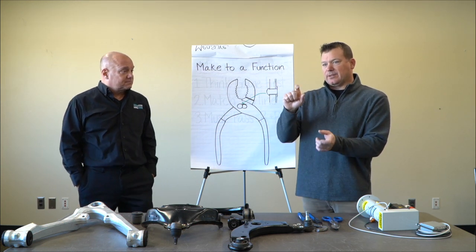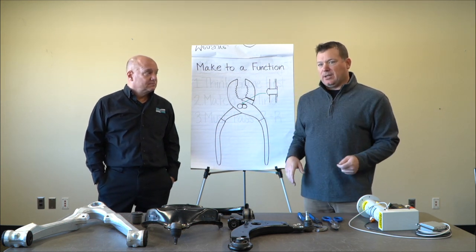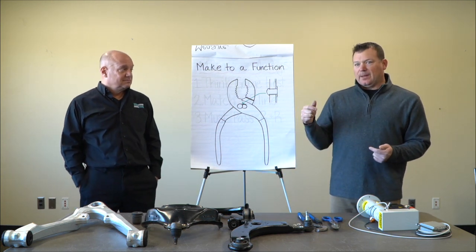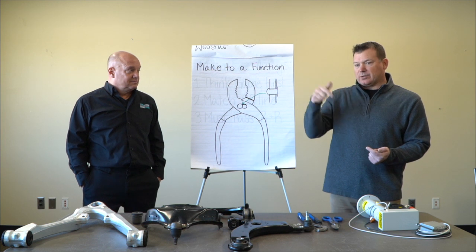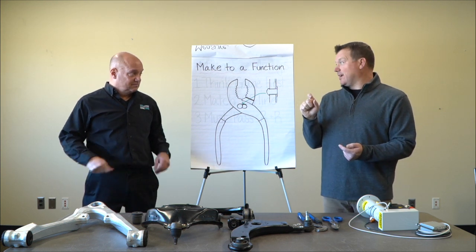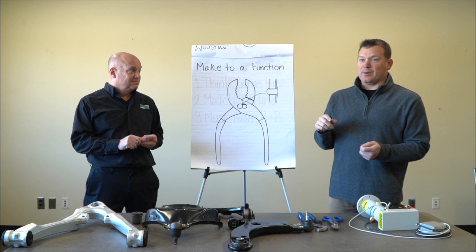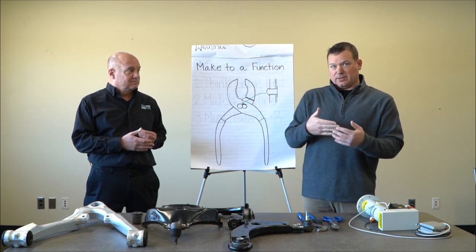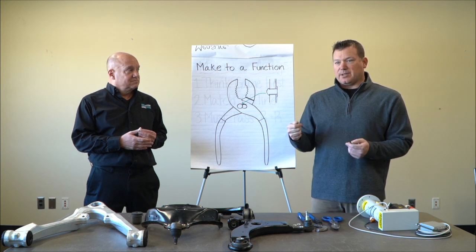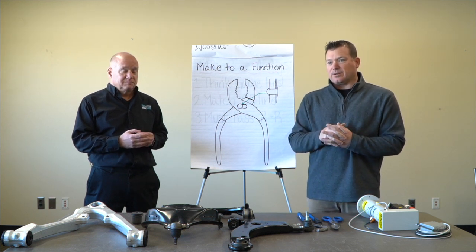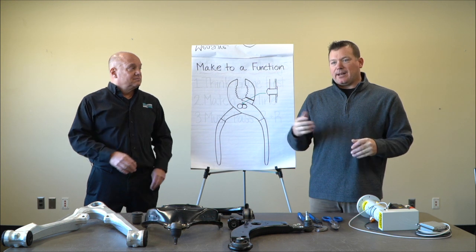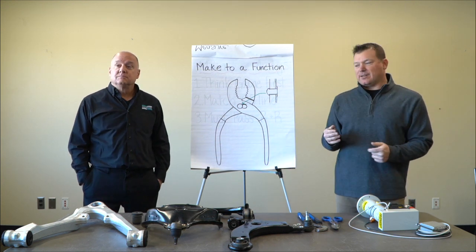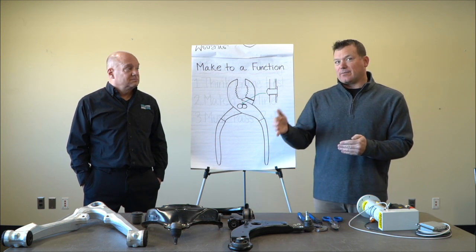There's actually two rivets on each side of this hinge, and I don't have that part here. But same thing, we actually crush those rivets. We do measure the rivet height on that, just because it's information they want to have, but it's not really relative to how it functions. And then we use one of our smaller presses, because it's a very light force, to actuate that back and forth until it makes a good part. So a lot of times these applications aren't just one and done either. They basically require several steps.